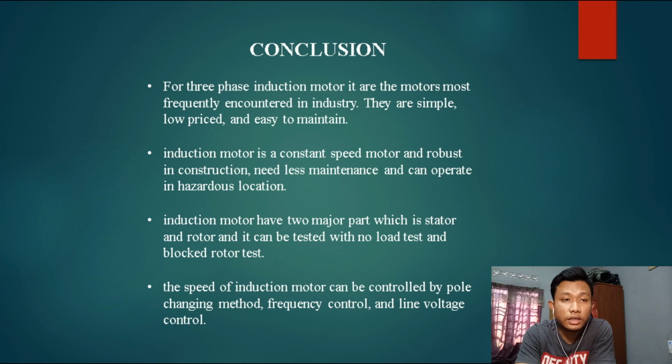Next, an induction motor has two major parts, which are the stator and rotor. It can be tested with the no load test and blocked rotor test. And lastly, the speed of an induction motor can be controlled by the pole changing method, frequency control and line voltage control.